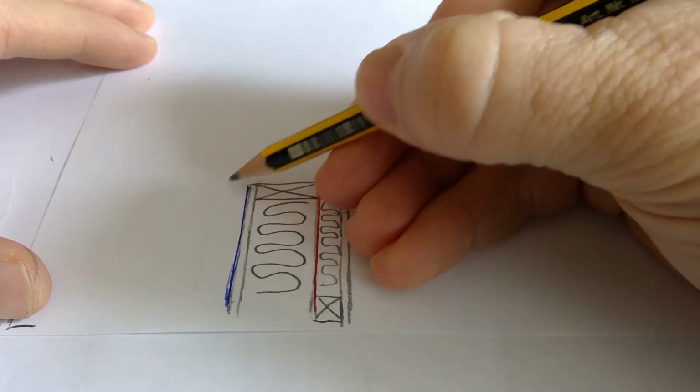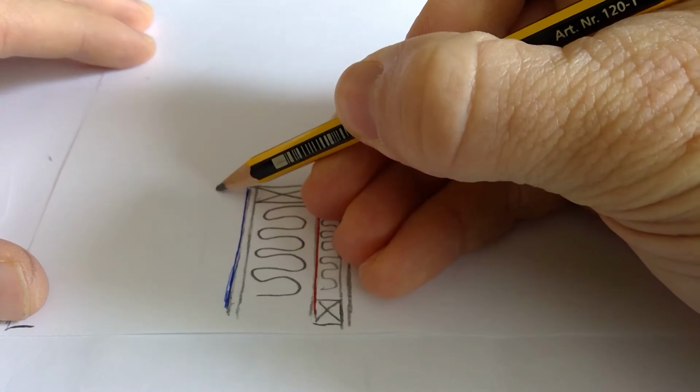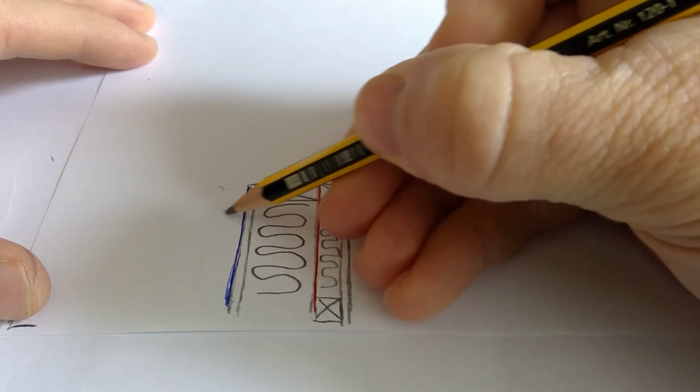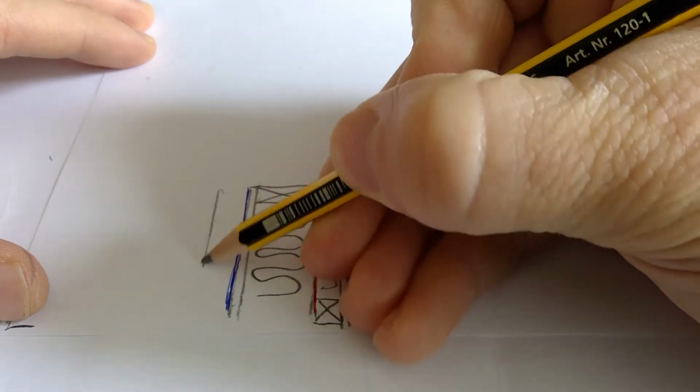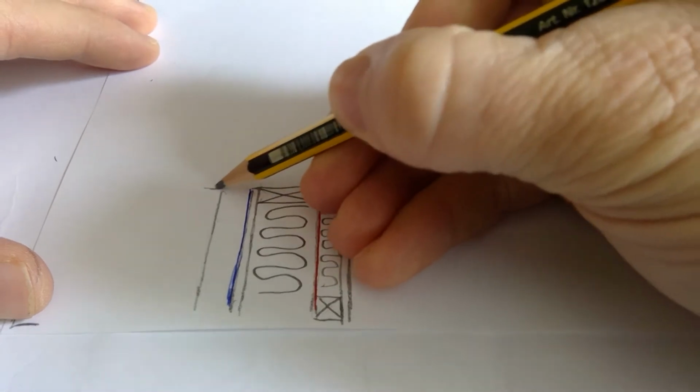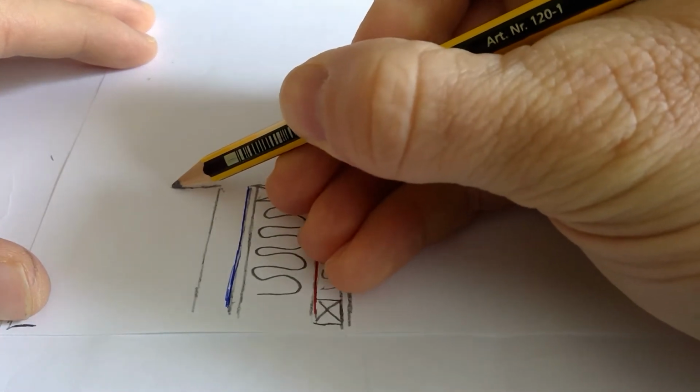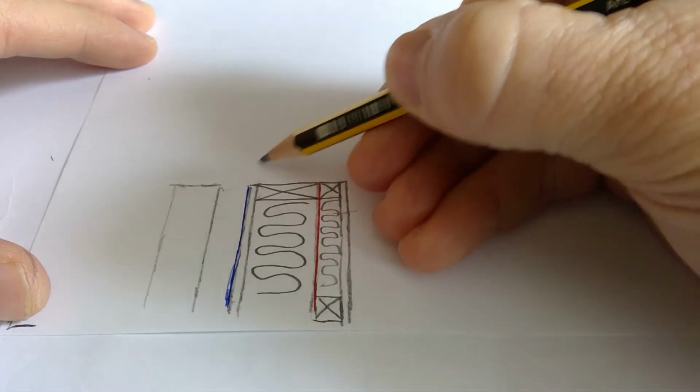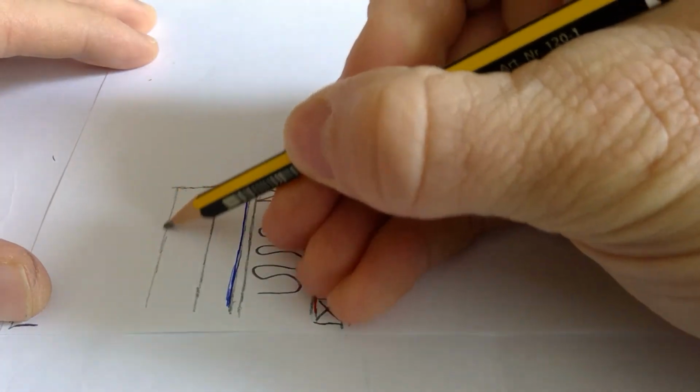All right, now we have the external leaf. I'm going to draw the external leaf. So there's always a 50 mil cavity, by the way. External leaf is blocks. Again, everything to be drawn lightly first of all. I'm going to draw it lightly first as well, just because the roof might be coming down over it. But there's the external leaf, and draw your blocks in if you want.